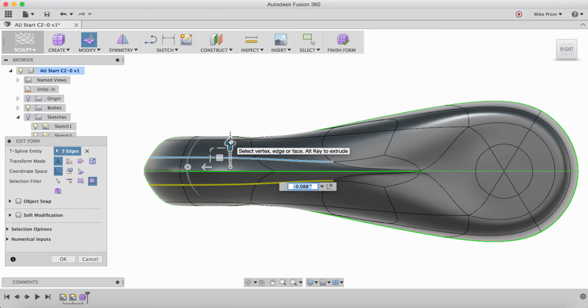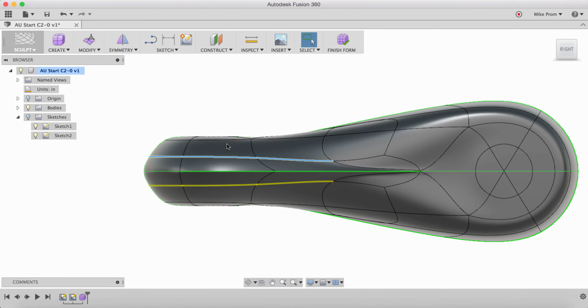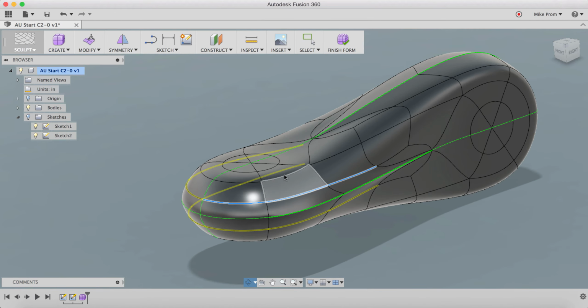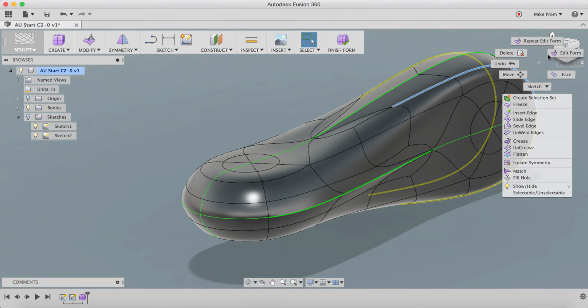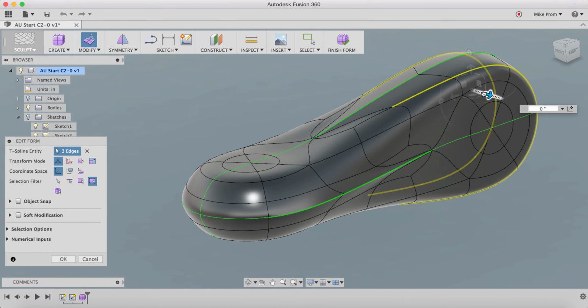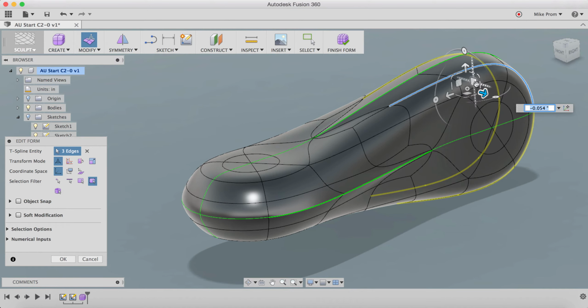I would challenge you to explore different ideas, scale them up, scale them down, and see how, when you have a line that's creased and you drag other lines close to it, that affects the curvature and the blending between the two. Since I would like to keep this symmetric, every time I do something to one side of my model, I'll repeat it to the other.